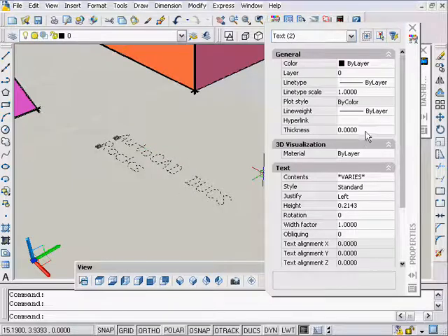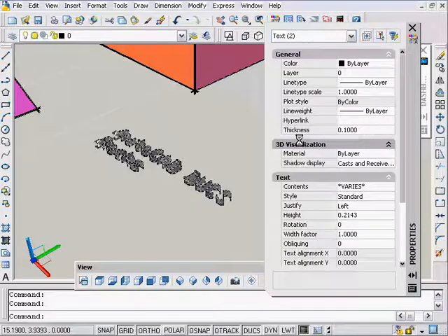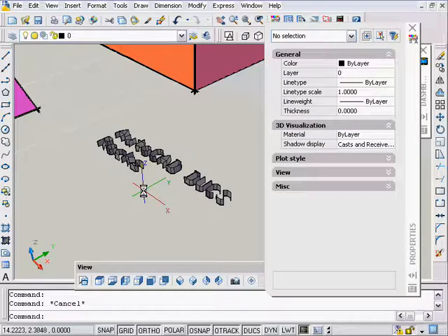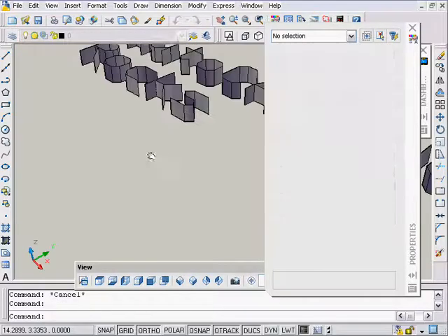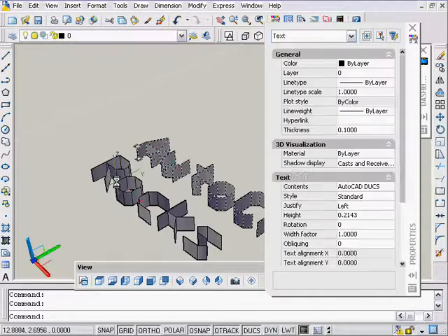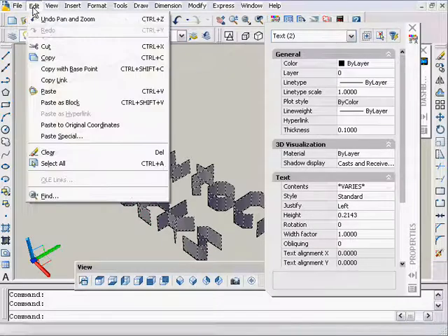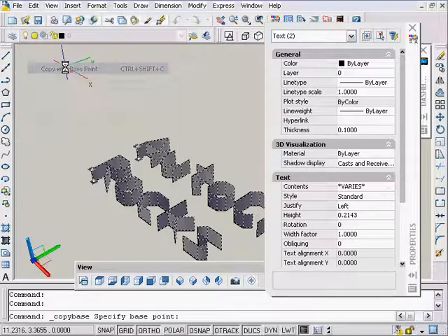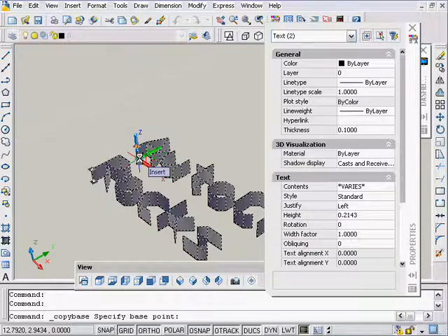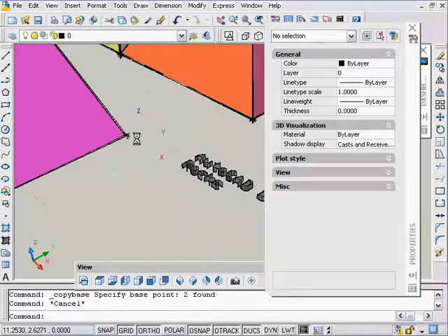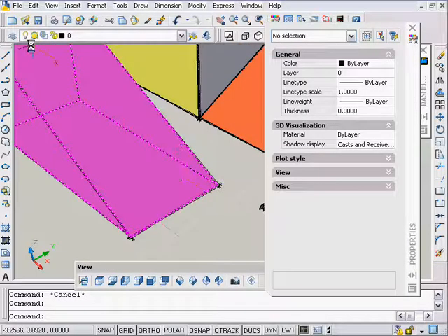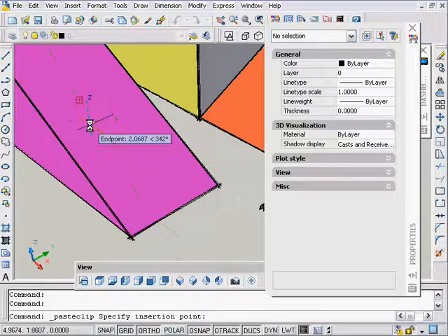And then go down into here, and then I'm going to just kind of get sneaky and click on these two pieces of text because they're D text. I can give them thickness of say 0.1. Okay, now I can go up to this text, or this could be anything. Okay, click on these two objects and say edit, copy with base point, and then maybe pick down there as my base point and hit escape. Okay, and now I can go Control V.